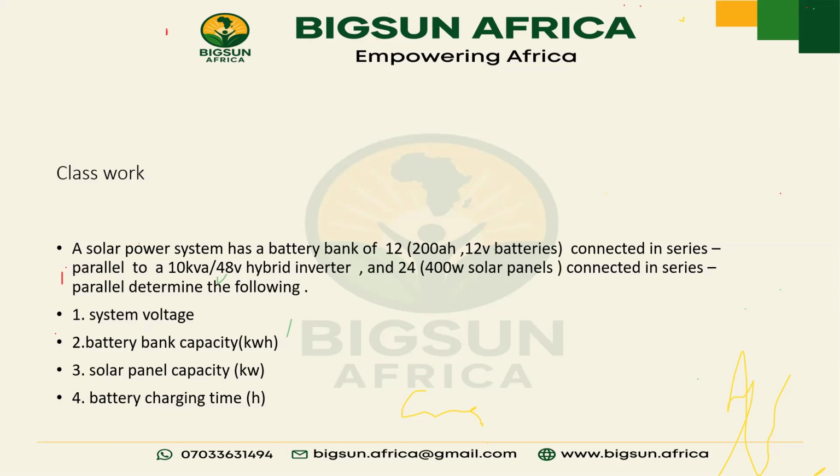So the charge time is going to be now 28.8 kilowatt hour all over what? 9.6 kilowatt. That's 2.7, approximately 3 hours. You said the battery bank capacity in kilowatt hour is what now? In kilowatt hour it is 28.8. Divided by 9.6 is going to give us 3 hours.